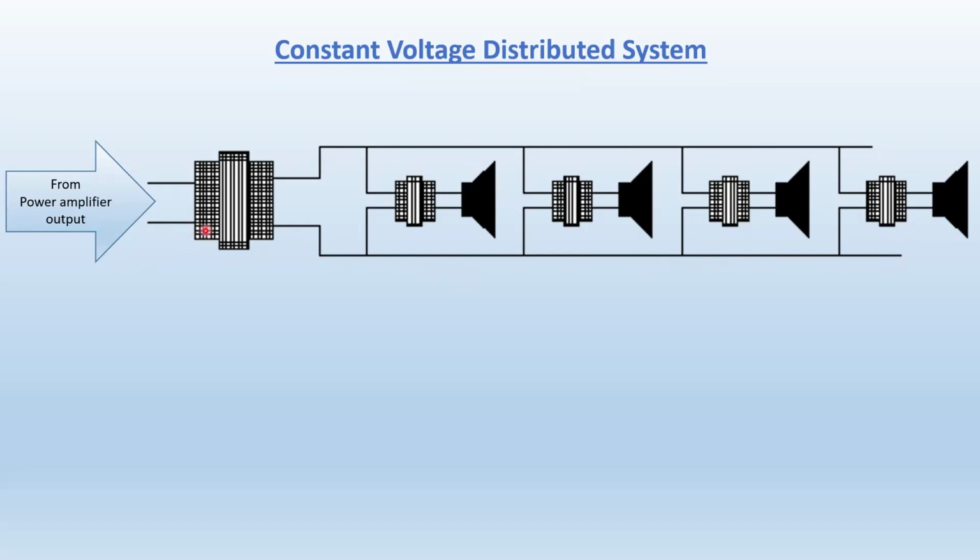Now, what we have here is something that's called a step-up transformer. And it transforms from low impedance, because 8 ohms is considered to be low impedance, compared to the high impedance. So there are not too many windings here, a lot of windings there. We're going to have high impedance here. So here will be about 8 ohms, and here will be maybe 1200 ohms or something like that, in the range of 1200, 1500 ohms. So it is a step-up transformer because it steps up the impedance.